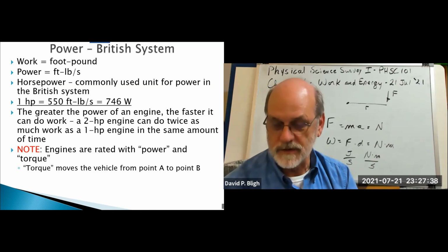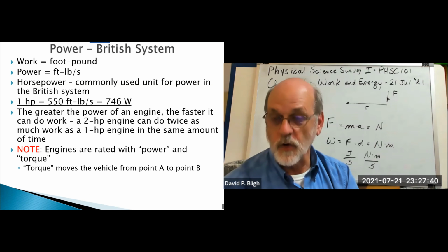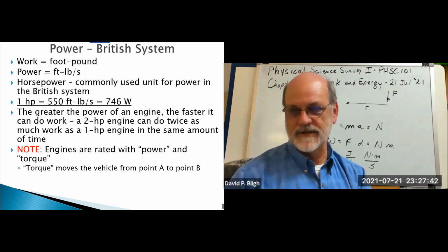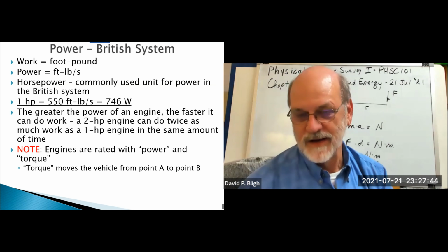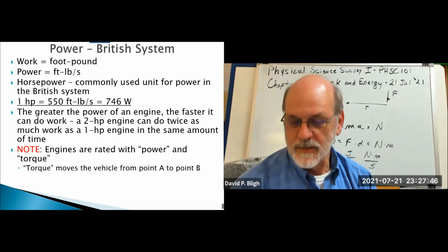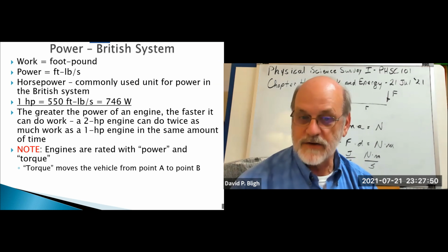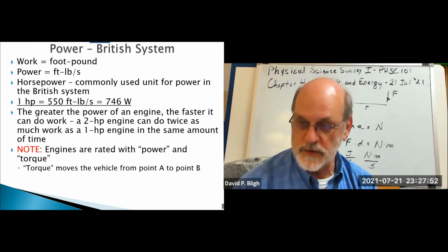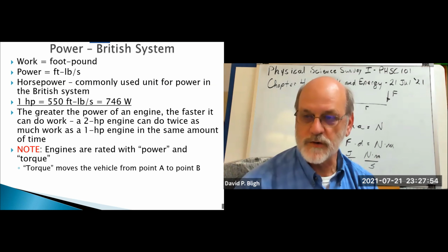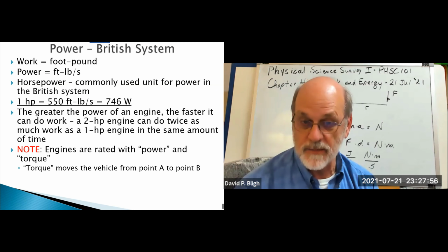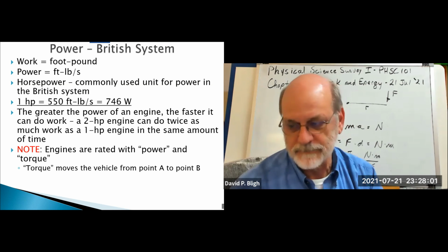There's not enough torque, so the horsepower is irrelevant. It's not going anywhere with that engine. But if I have a large enough engine under the hood and the torque is sufficient, the force will move the truck, then the horsepower, the power of the engine becomes relevant and says, all right, now that it's moving, how fast can we get there?